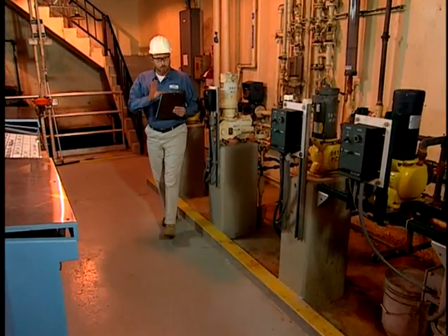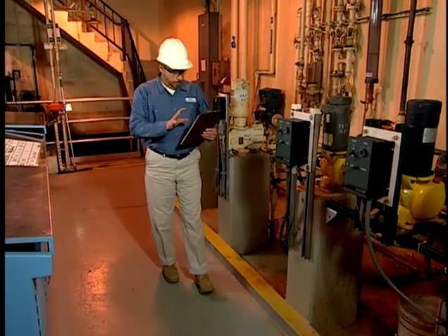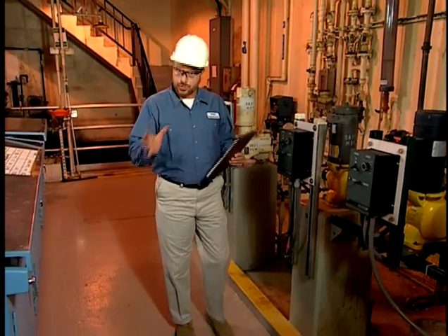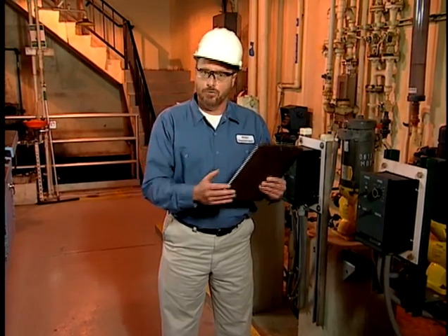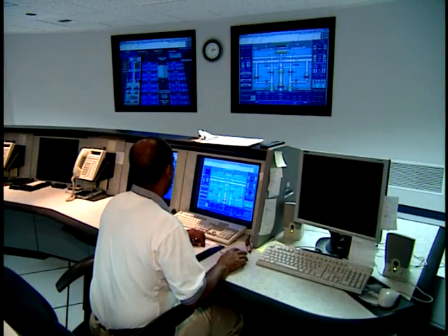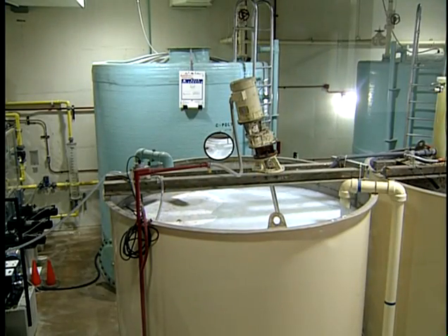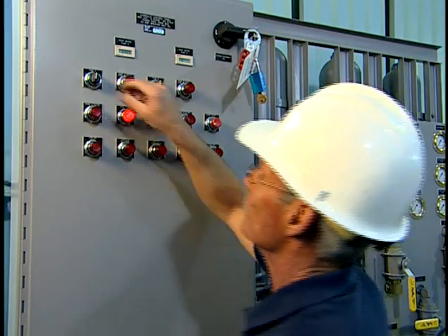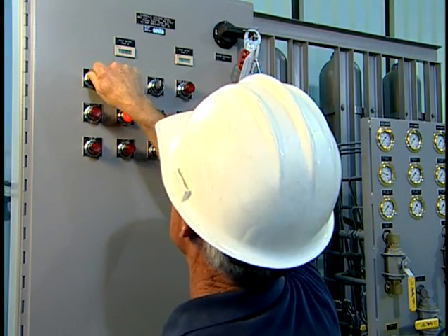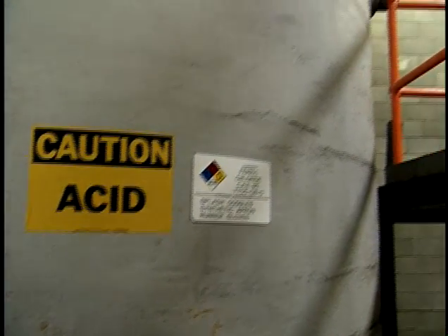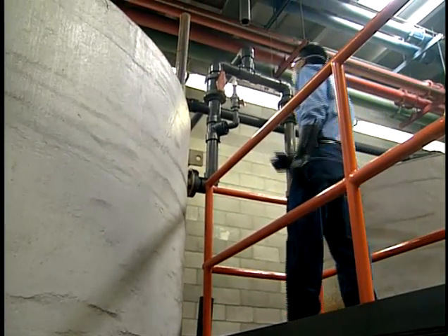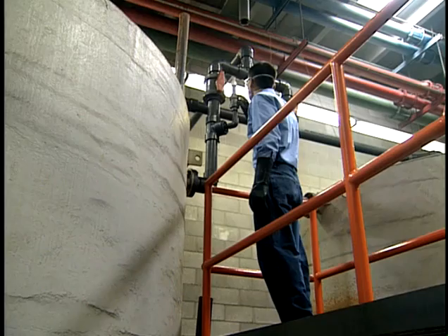Another key component of process safety management is to develop and implement written operating procedures that are consistent with the process safety information. This provides clear instructions for employees conducting activities involved in each covered process. Operating procedures should include steps for initial startup, normal operations, and temporary operations. Emergency shutdown procedures should be included with assignments for each operator in terms of shutdown responsibilities. Emergency operations and startup following an emergency shutdown should also be included.